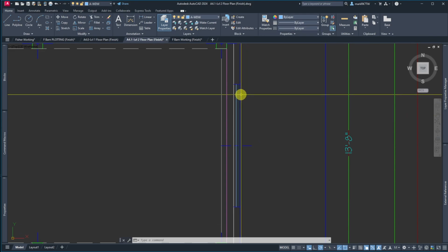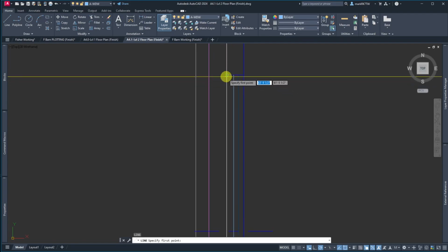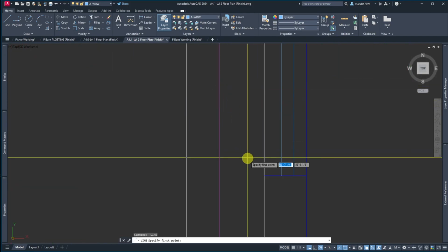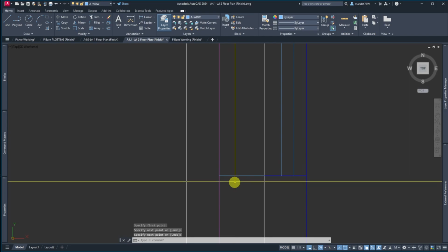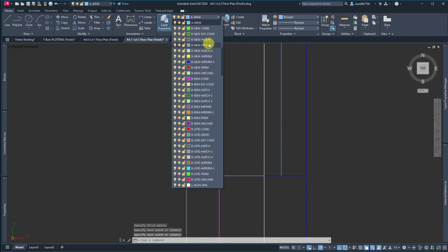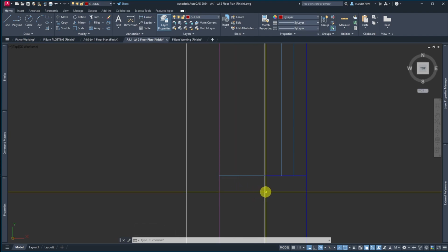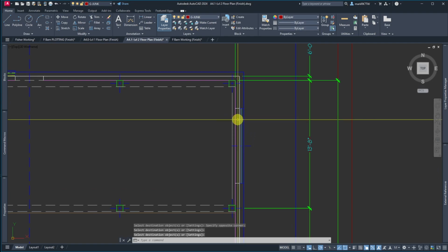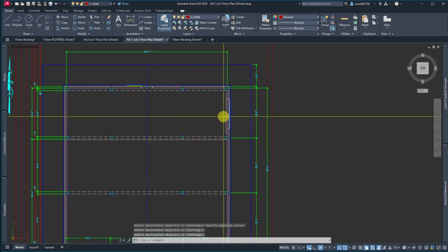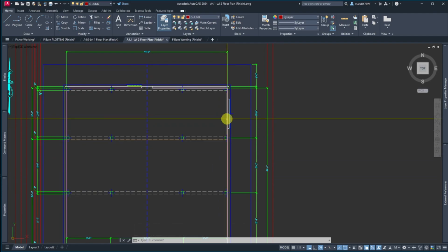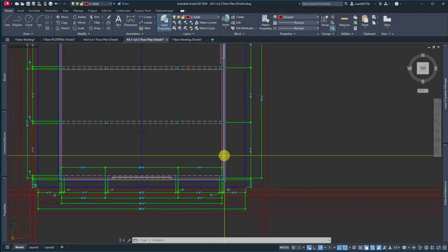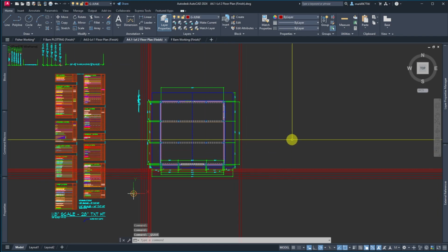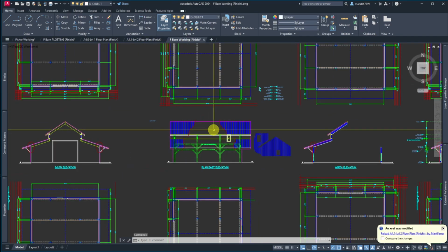So that window's pretty much done, except we need a line from here to here, and then one from here to here. I'm still on my A glaze layer, or A window. I didn't change back to my G junk to make sure that it sticks out so that I remember that I want to put these on their proper layers. So this goes on that exterior wall layer. Now I have that one, and this distance is different. If you remember, each of these is different from each other. But I'm just going to save this because this gets repetitive, and we are just over an hour already. So I'm just going to show you how this goes real quick.